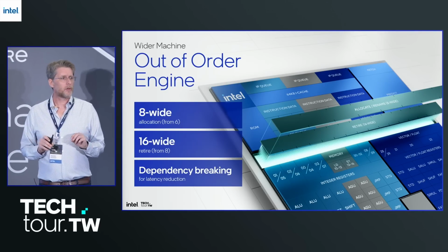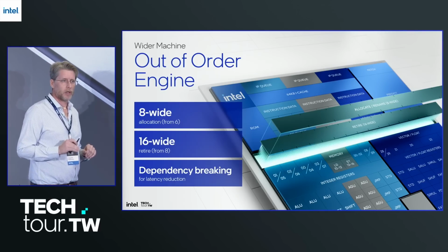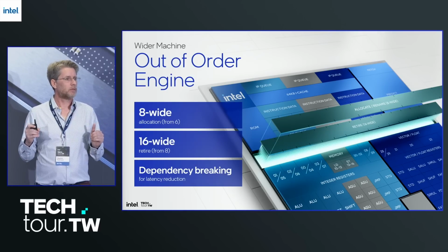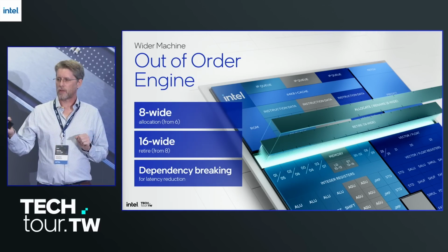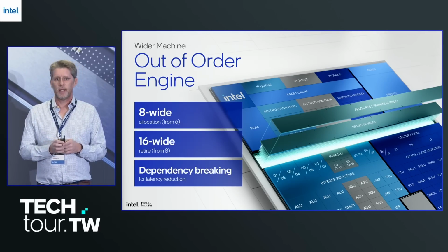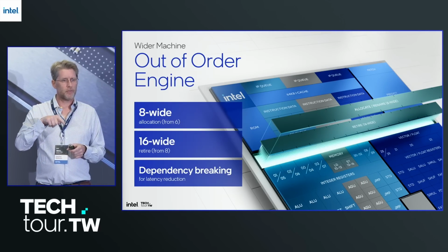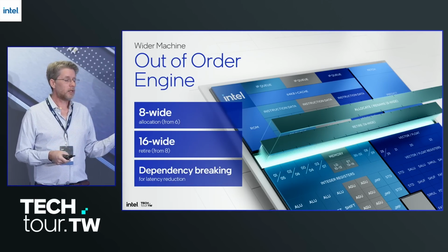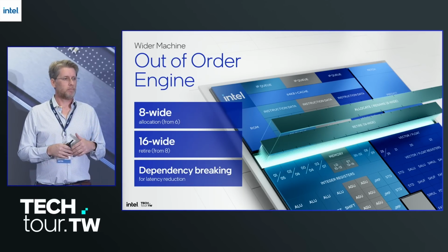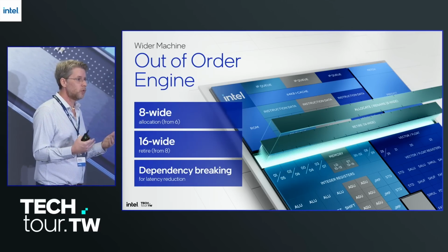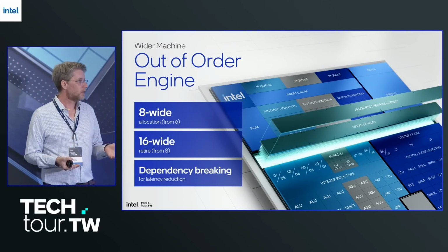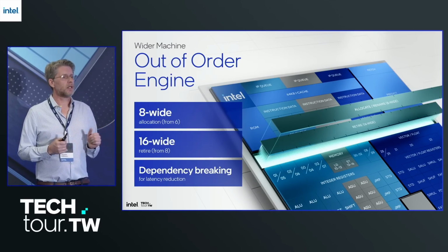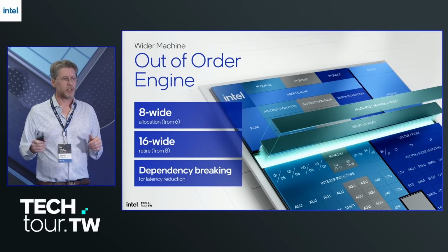Okay, the third one, in a perfect microarchitecture, you would end up with what we call the critical dependency chain. So I have one instruction that feeds another instruction that feeds another instruction, and in the end, with infinite resources, you find that dependency chain. So here, we've continued innovating and having more ways to actually break that dependency. So even though 2 instructions appear to be dependent, we can know that we can get the data from somewhere else. A classic example would be a zero detection, an idiom.